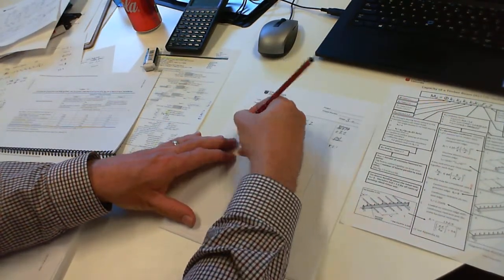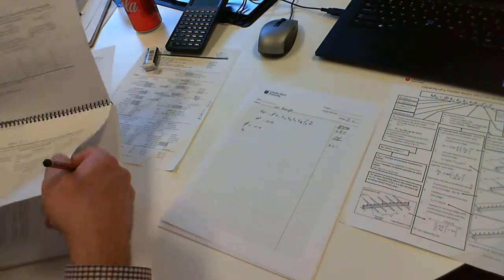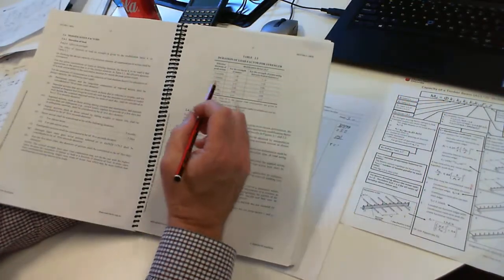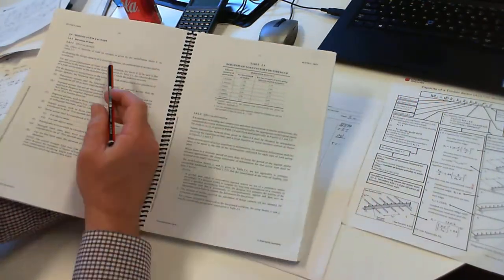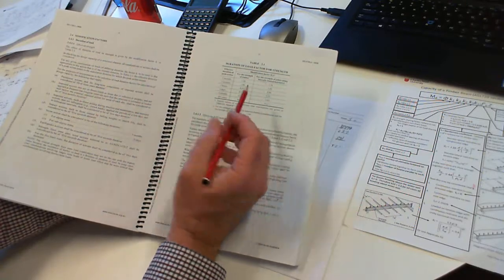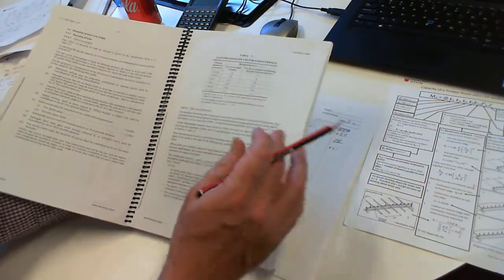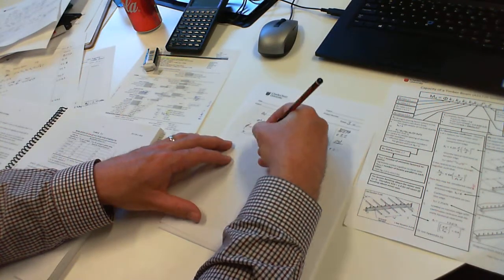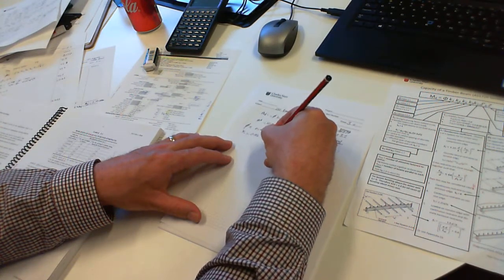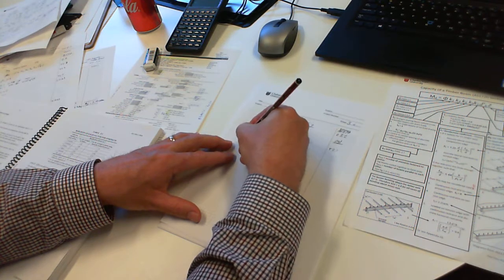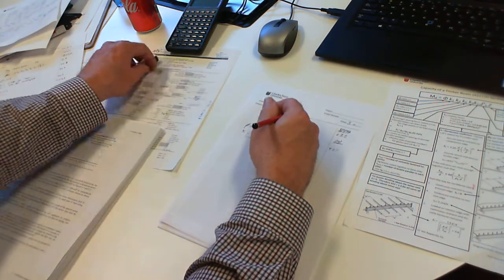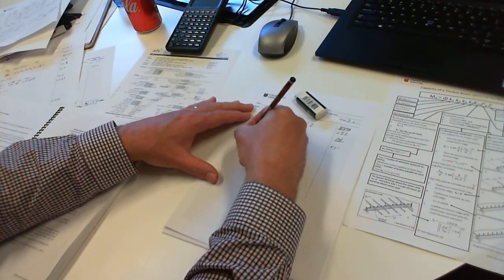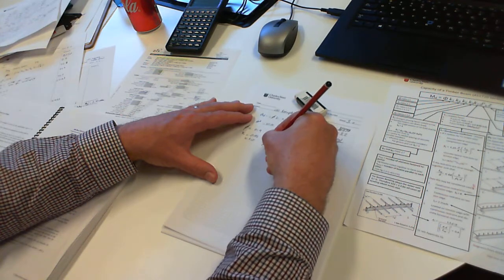Alright, let's look at our K1 factor. Our K1 factor comes from table 2.3. There's table 2.3, and we know that snow in a non-alpine area, if you read in this list on this side, is 5 days. So we're going to take a factor of 0.94 for snow. While we're here, because we're going to come back later and do the uplift, we know that the uplift is a 5-second duration, so it's 1.0 for uplift.